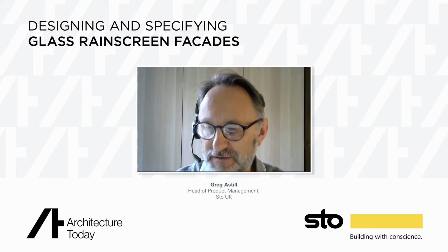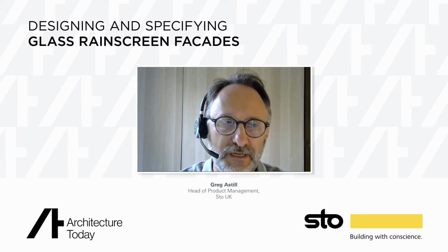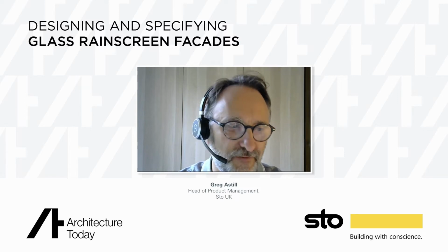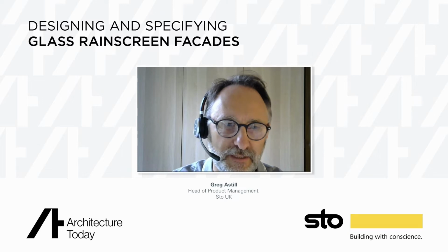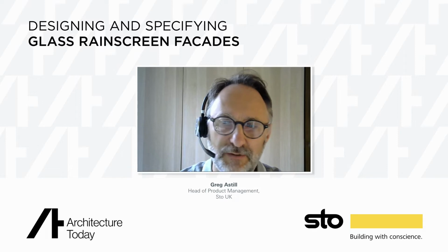The panel typically uses, the only variation really is 6mm or 8mm glass, and then we have around 2mm of adhesive and a backer panel onto that. So the total depth of the panel is 22mm with that build up.